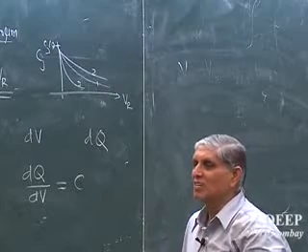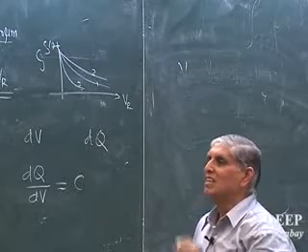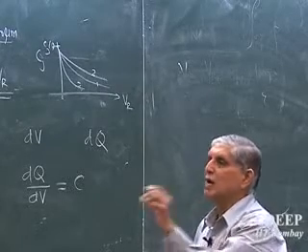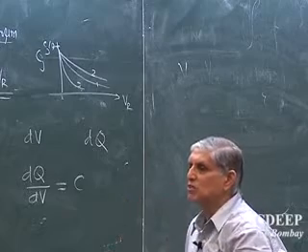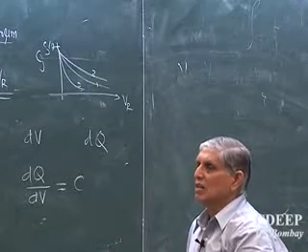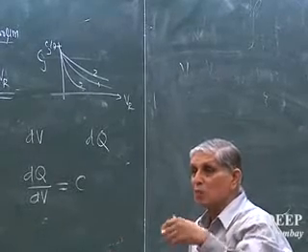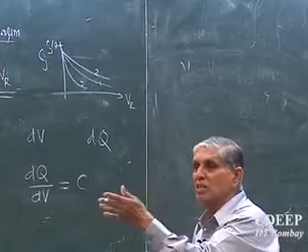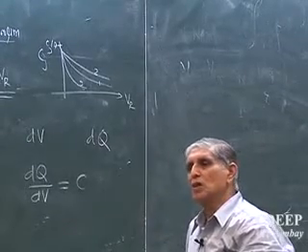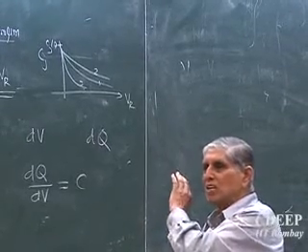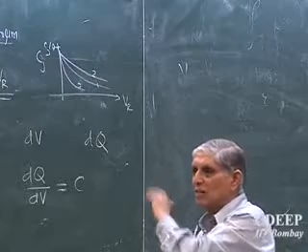So for a given application, the dopings are adjusted so that the bands are adjusted: which band, where to where, which frequencies you want to tune. In that case, the corresponding doping, which will give the corresponding W variation, will be applied. Is that clear? Is the definition clear of why dopings change capacitance?